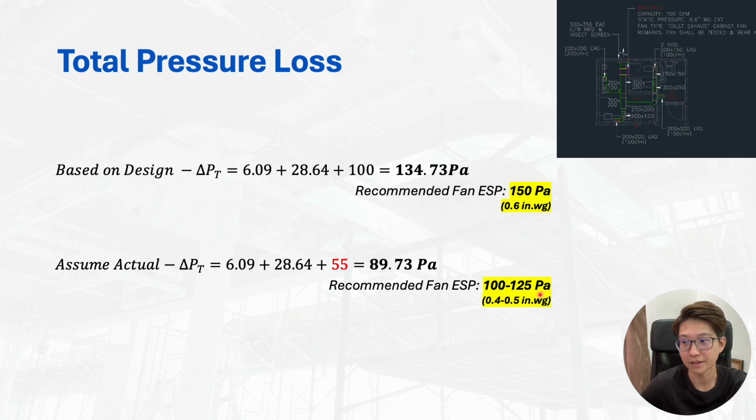But for reference, if we are talking about a very big smoke spill fan, a few thousand CFM, comparing 0.4 inch water gauge and 4 inch water gauge, 10 times, the price of the fan itself could be double. Usually double, I see it's double lah.